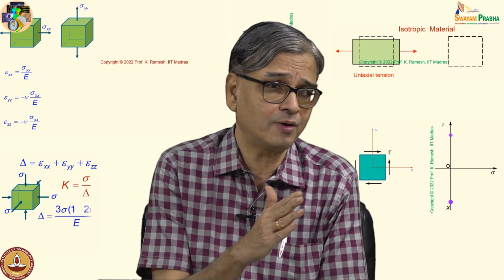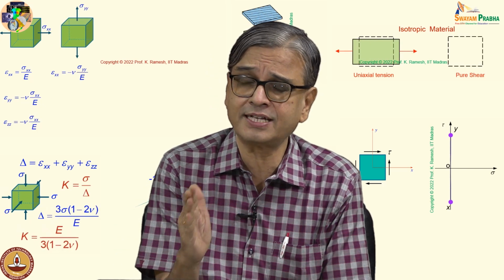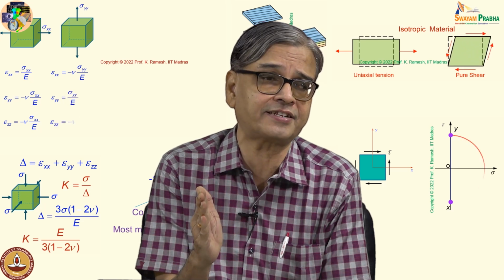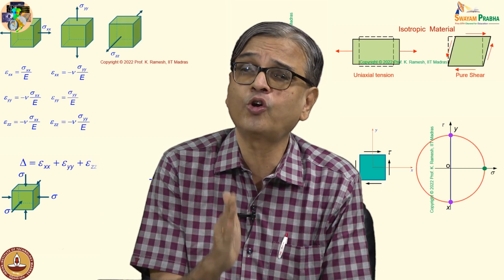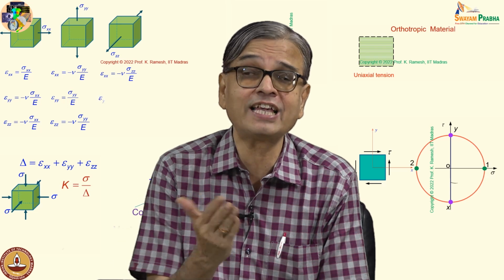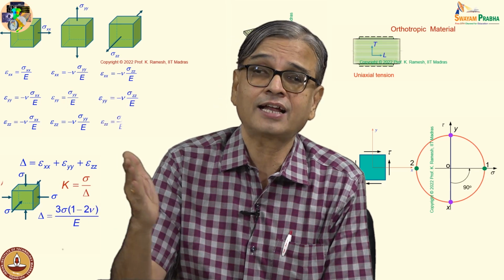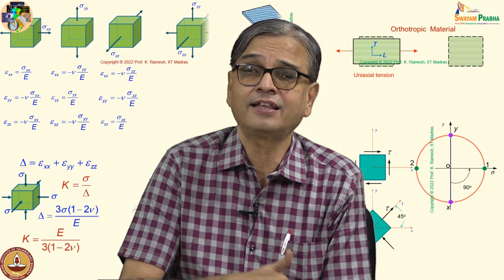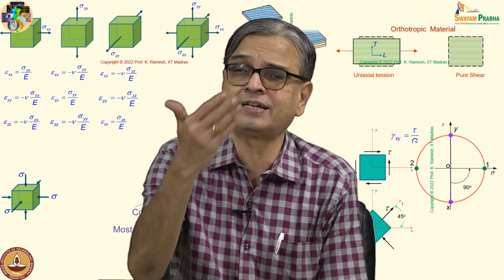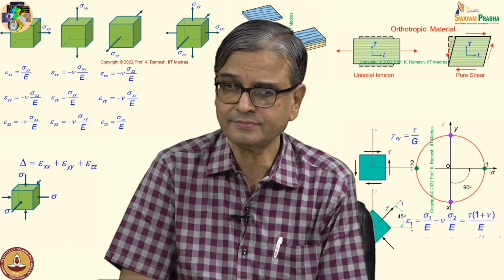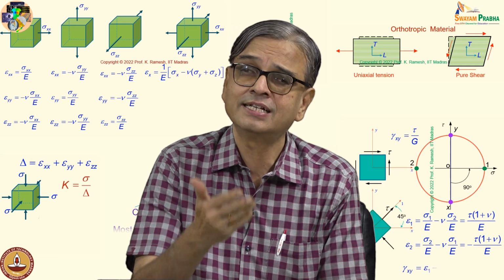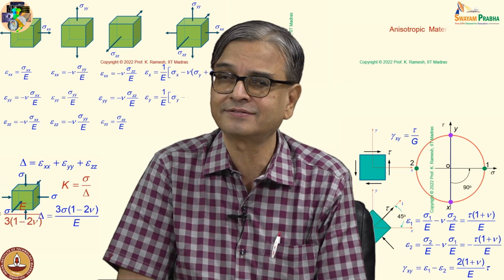And people have looked at all of this. See, the moment you want to go to plasticity, history of loading becomes very important. You may think why history is important. They are transporting material in a truck and then truck has an accident and all the material fell on the road. That means they have an impact load. Some of them would have deformed plastically.